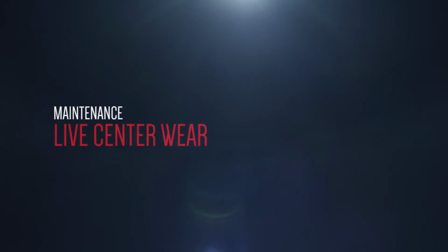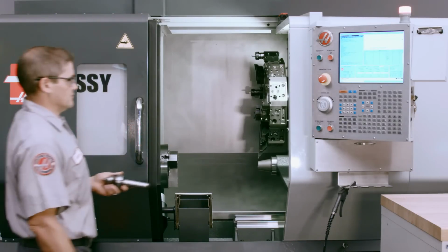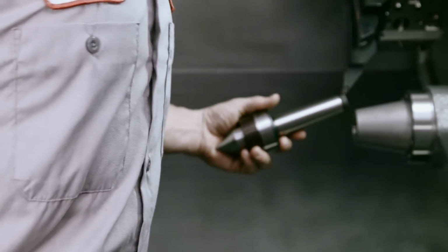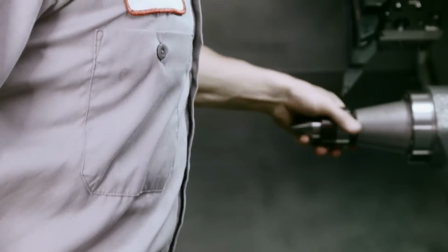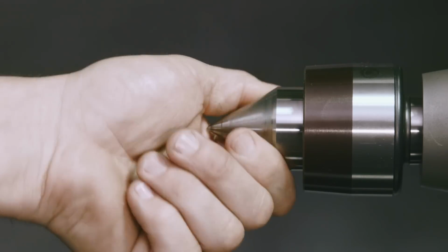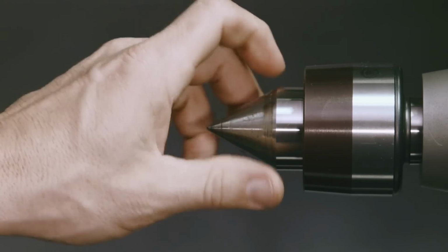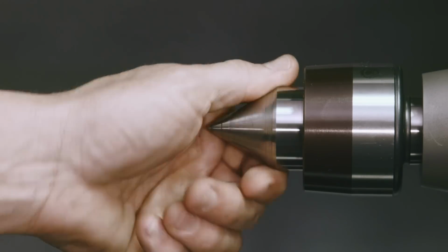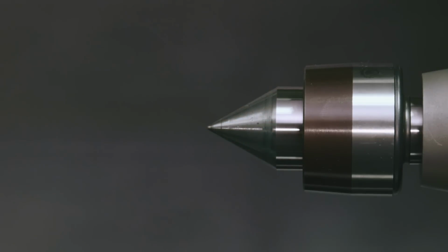Live centers do wear out, especially if they are mistreated or abused, so take good care of your investment. Let's check the condition of this used center. First, we're going to check out how smoothly the bearings roll. Rotate the tip 4 revolutions, and then keep rotating in that same direction, feeling for smoothness of rotation. If it's smooth, the bearings are likely in good condition.